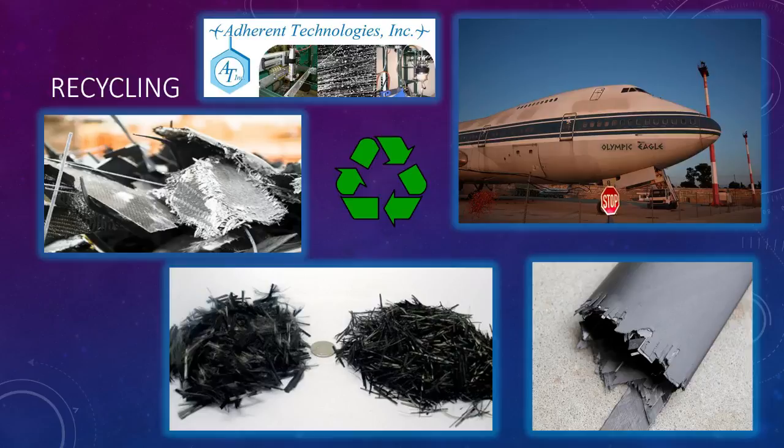Here, carbon fibers present some unique difficulties for recyclers because of the complex nature of the product. A composite can be made from a number of materials that are much more difficult to separate, and in the case of thermoset composites, cannot be reclaimed through a melt process. Since the idea of recycling composites was first conceived, the greatest challenge has been to develop a profitable recycling process.